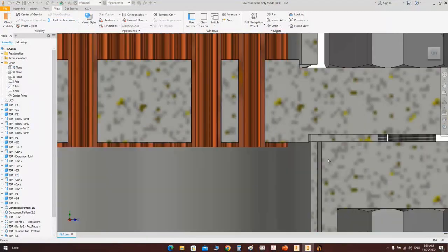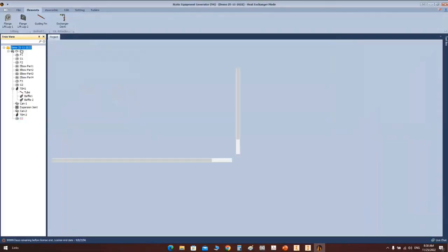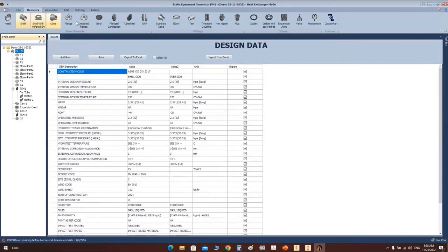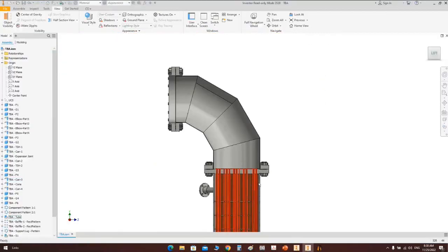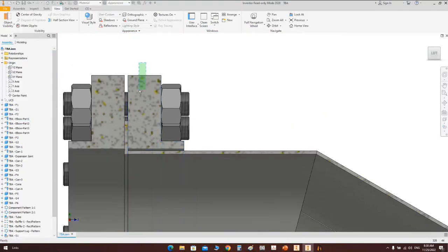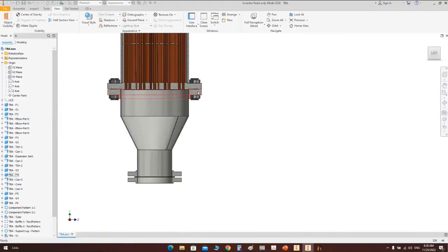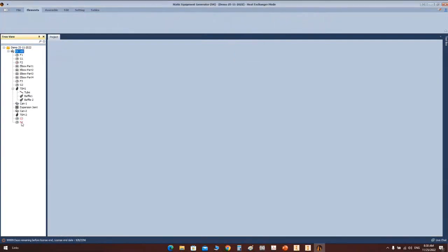this one, another body flange, another shell course. So after adding this gasket, let's add another body flange. So from here, let's add the design flange. It's F4, and it looks like F2. Okay, if you come back here, this flange looks like that one, the same dimensions as that one. So we will make it with the same dimension. So directly you can select same as F2 from here to avoid repeating dimensions again.